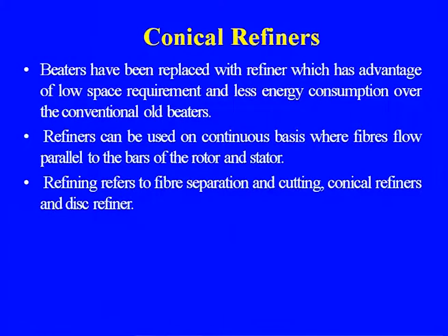Beaters have been replaced with the refiner, as I told you, which has become a more energy saving device and has the advantage of low space requirement, because the space required in the case of a beater is very large. In the case of the refiner, the space requirement is less, and it has less energy consumption than the conventional old beater. Refiners can be used on a continuous basis, where fibers flow parallel to the bars of the rotor and stator. Here the beaters are a batch process, while refiners are a continuous process.